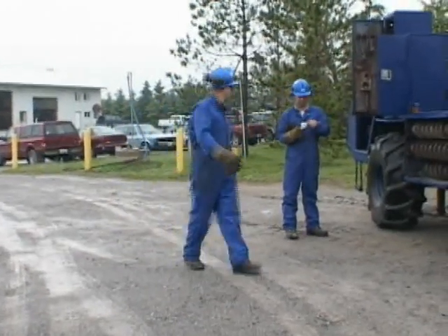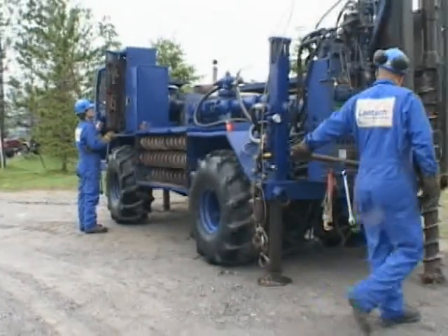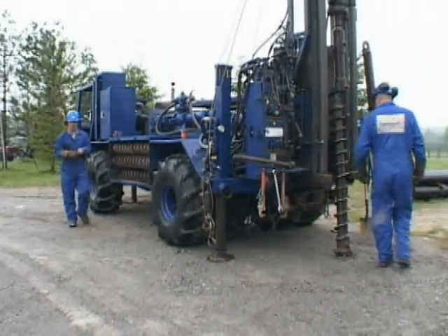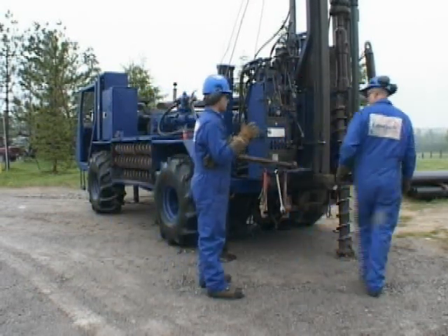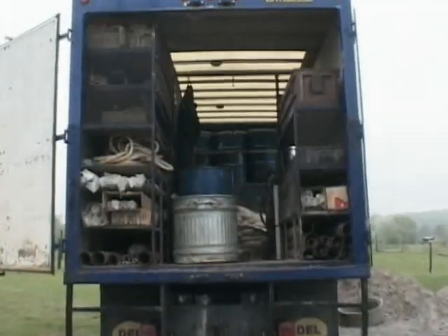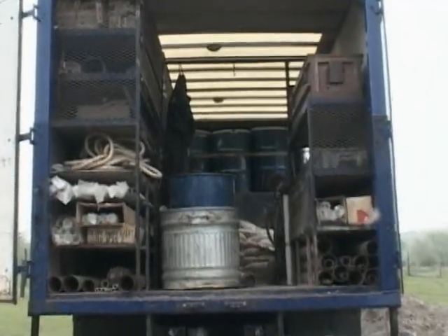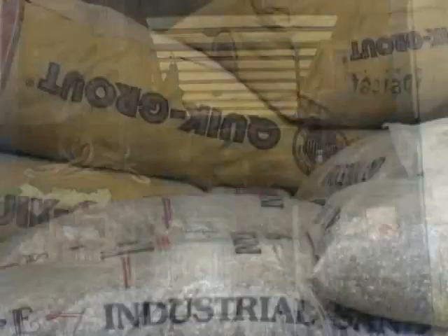These rigs are usually powered by deck-mounted engines and are capable of extremely high rotational torque loads to the drill string. Due to the large surface area of the augers, these machines require significant energy in order to advance the hole. The support equipment is often self-contained or can include a separate vehicle which carries the supplies needed, including grouting materials.